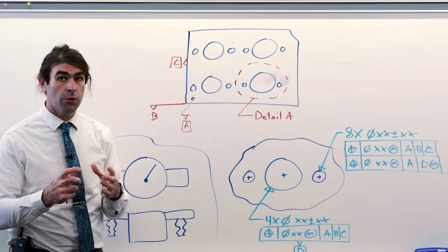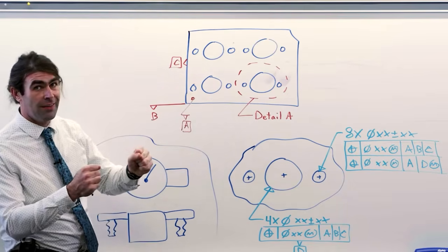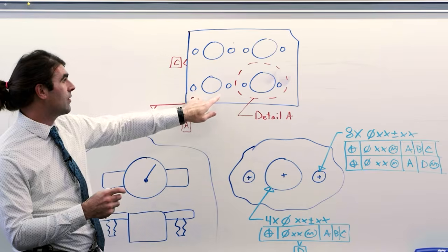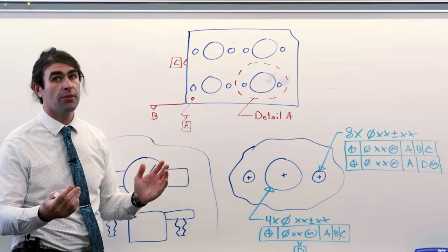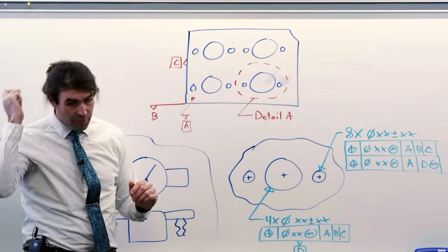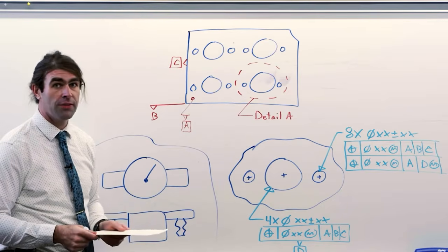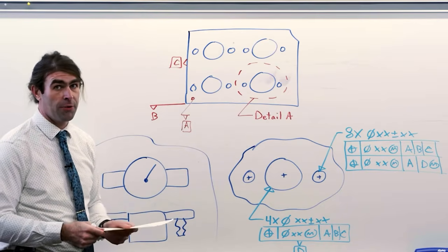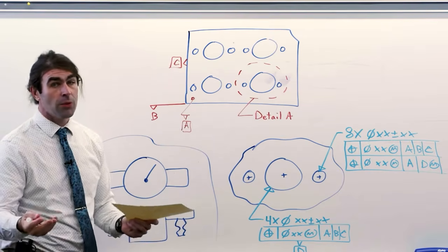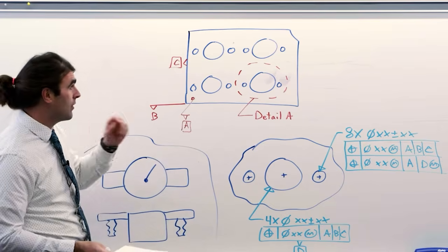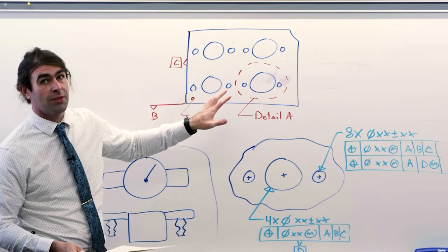So what we're looking to do is control these 2 holes to this big hole very tightly, but to allow each of these little planetary systems to kind of float around a good bit for ease of manufacturing. If you think of somebody making this, right, maybe they're only making one and they're at a punch press and they're just doing each pattern one at a time. They're going bang, hitting one, then the other, then the other. It doesn't really matter how they make it, but it's probably easier to make these 3 in line than it is to make all of these perfect.